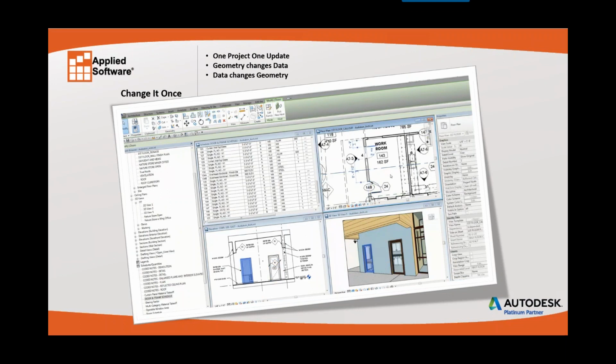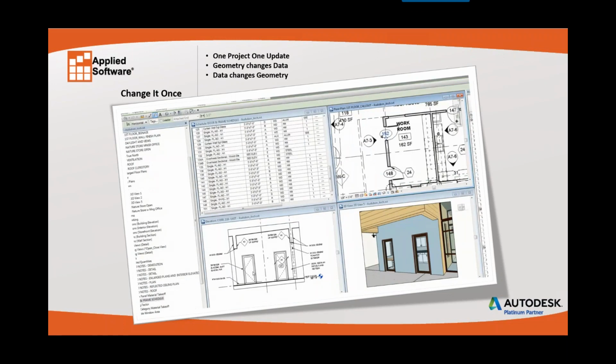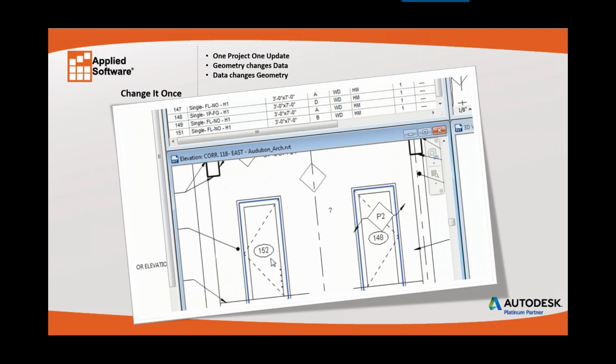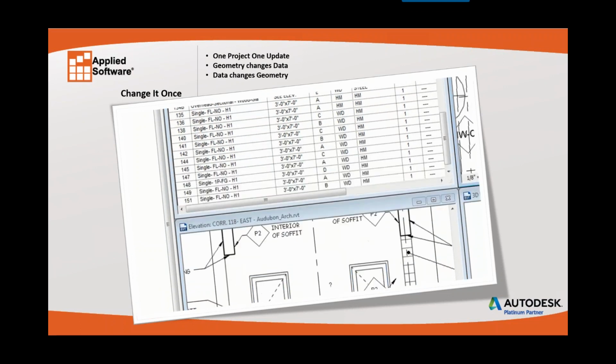Now I need to add another door to the other side. Simply by mirroring the other door, now I have two of these doors. Notice that I've highlighted them here. The door itself is smart enough, it already has a door tag. That door tag information is stored within the door. The tag itself just reads the information from the door and automatically adds it to the door schedule.